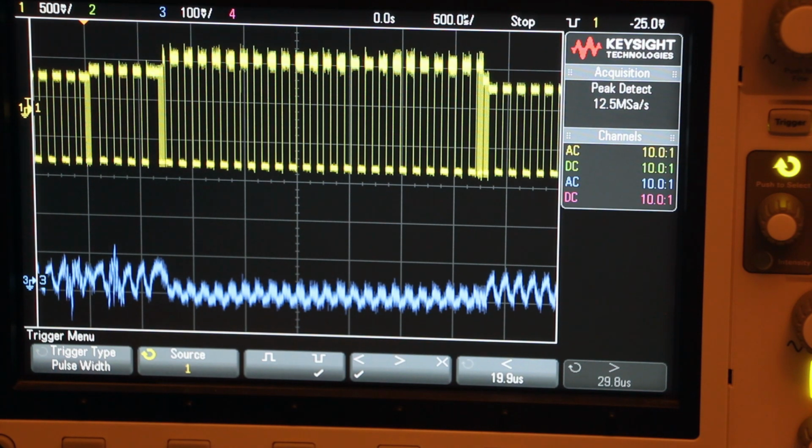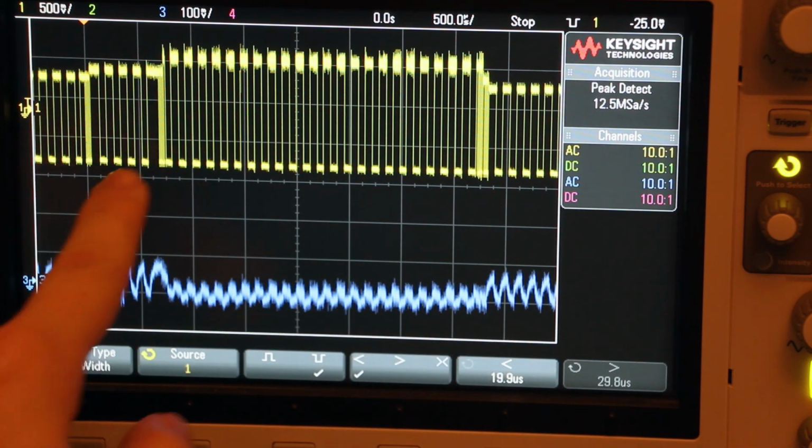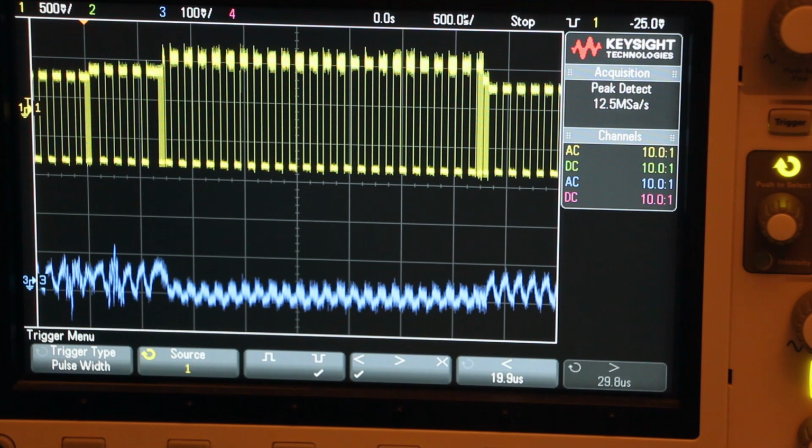All digital electronics require a clock so that they can have a good reference for time passing and advancing from state to state. And here I suspect that the micro that's in the bung is providing that clock through the power line along with the data. So this clock remains stable, and it's only interrupted during these brief periods where there's data on the line. That's something that I think we're going to have to re-implement when we do this ourselves, but we can have a play and we can try providing no clock or a clock and see if it works without.